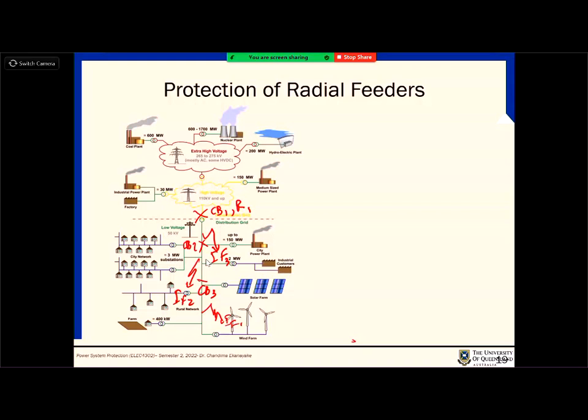This is the point where Noja Power and all these companies came into the market, probably in the 2000s. The reason is that they came up with a design. Earlier circuit breakers were bulky and you just installed them in the substation. But they came up with a solution saying I can put one on the poles in intermediate sections. Probably not only them, there are Siemens, ABB, probably everyone has something.